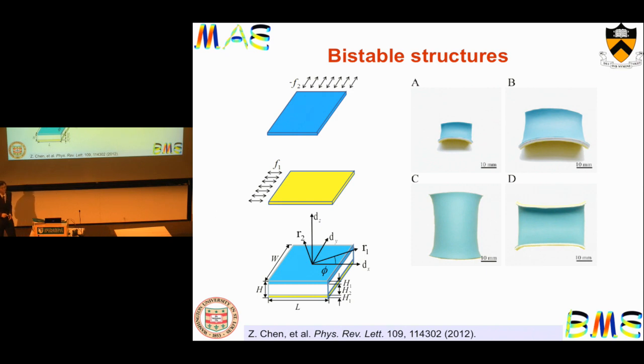And we can actually manufacture such a structure by a 3-layer experiment. So we pre-stretch the top and bottom layer with the same strain. And we sandwich a square sheet in between, so they're bonded together and let go. It's not surprising that the system will deform into a saddle shape because of the nature of the driving forces. Okay?